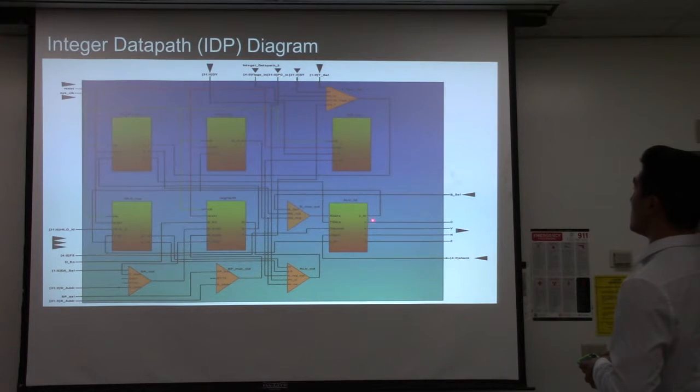And our ALU takes the Y-low 32-bit value, let's say after a computation, and it'll send it into the ALU register up here. And it comes out of the Q ALU and goes into the ALU out. And based on this mux, it can just write back into the D of the register file. This ALU out decides what can get sent back into the register file.